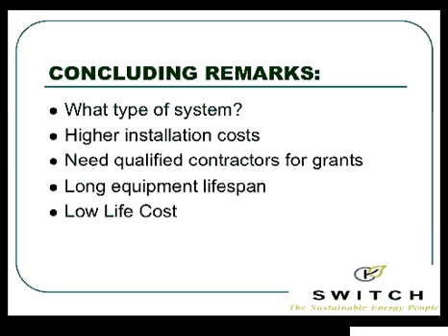Yes, it means that the fan is operating longer compared to the oil furnace. Basically, yeah, if you were supplying the same airflow quantity, yes. Even if you have bigger ducts? No, if you have bigger ducts, no, you're not. That becomes a design parameter. But if I had the same size ductwork and I'm pushing cooler air through it, then I would need to push that air for longer, yes, and increase my fan operating cost as a result.